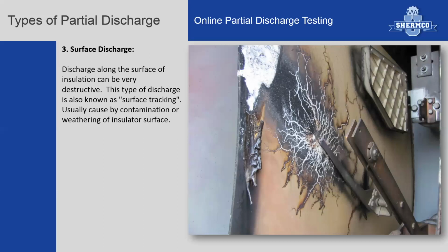Normally, the counteraction to this, inside the switchgear equipment, would be ensuring that the heaters are operating. We're keeping moisture and humidity levels under control so that contamination does not build up on the sidewalls or on the insulators and so forth. In the substation yards, corona transition into surface tracking may indicate that it's time to bring the station down, do a power washing, and re-waxing and conditioning of the porcelain, excuse me, went totally mind dead here, bushings. Yes, that was the term I was looking for.